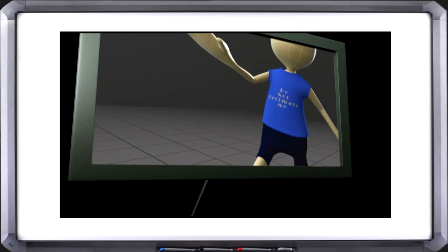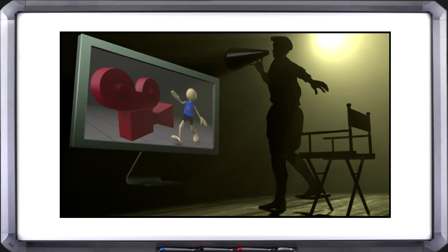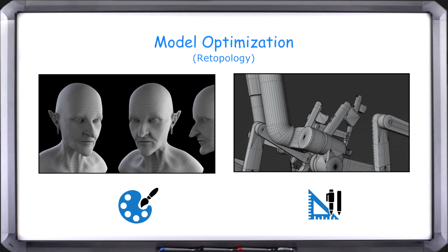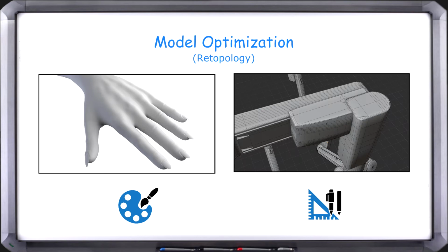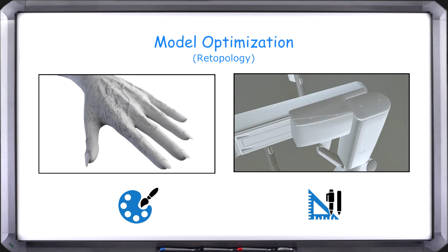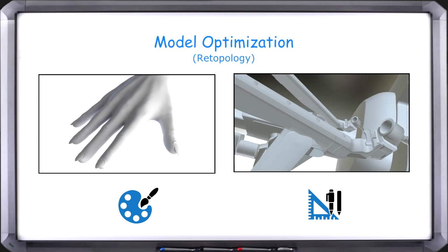So it should be noted that decimation should not be used on a graphics model that will need rendering in a scene. The end of this process, in all cases, is a point of no return milestone where the mesh is ready to be prepped to have the details that were lost in the retopology optimization phase added back to the model in a way it can be rendered in a game or VR environment.